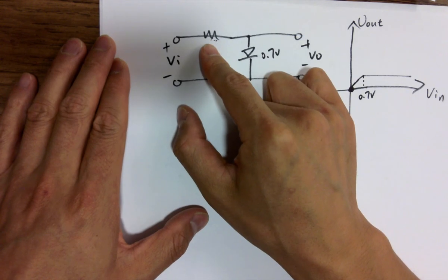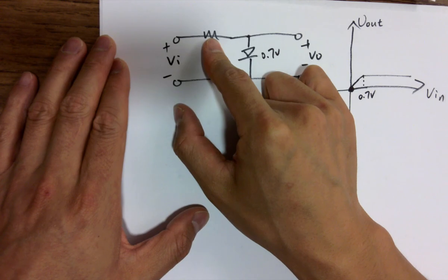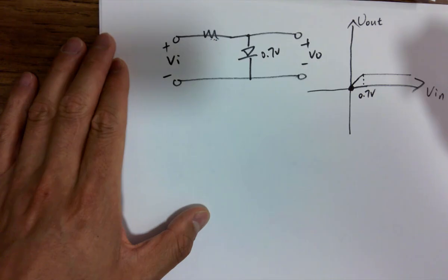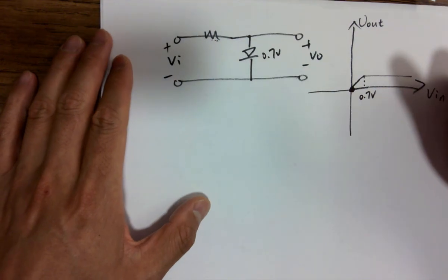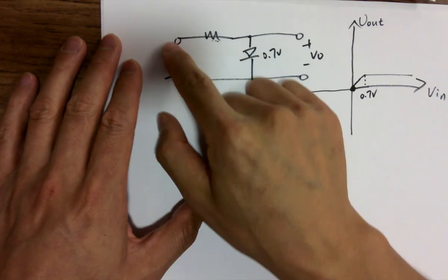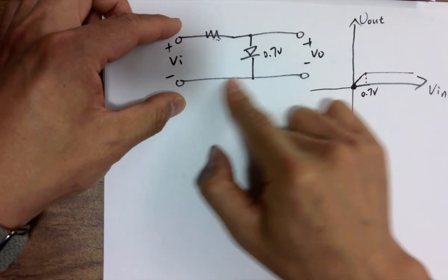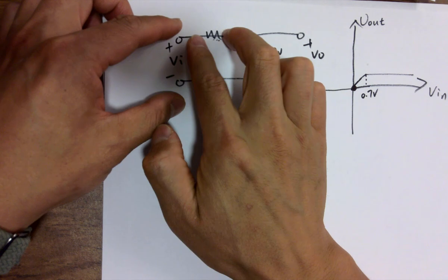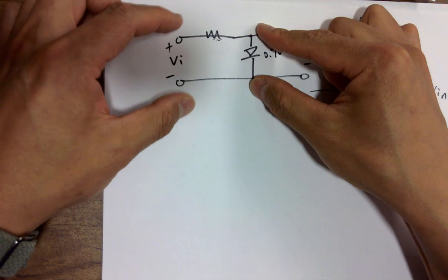So why can this resistor drop more voltage? It's so intelligent, it knows when it should drop more voltage. Is the current decreasing? No, the current is increasing. The resistance is not changing. The current is increasing, so the voltage is increasing. It's I times R. So when you have more voltage, you get more current, times the resistor, you're getting more voltage drop across this. But this is still fixed. It's not changing. Make sense?